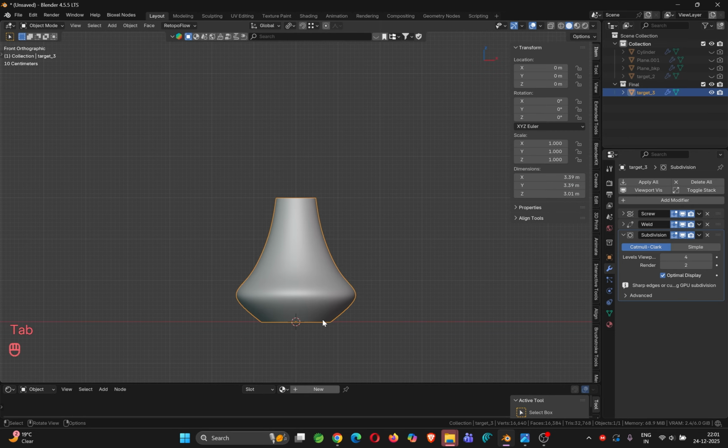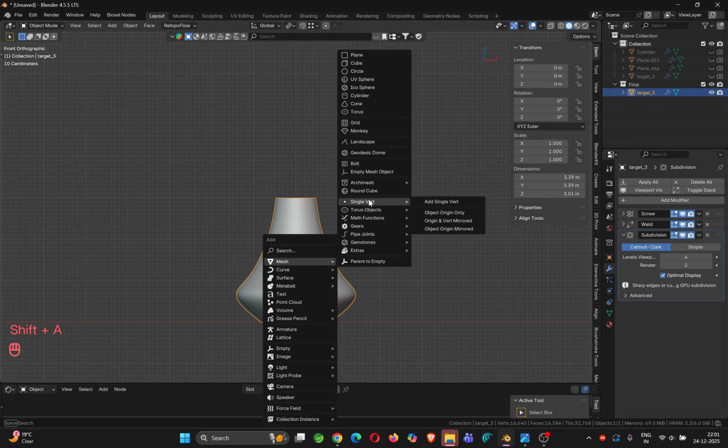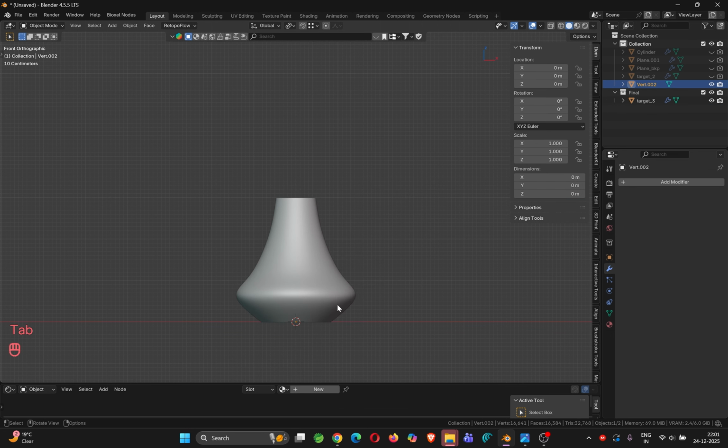We'll again start with a simple single vertex. Okay, single vertex I have added here. Now you will see, let me undo it a little bit again, whenever you create a single vertex, it by default jumps to edit mode, and it selects some other mode. Be careful. Watch it. If you see you cannot move that vertex, remember you need to go to here and change it.